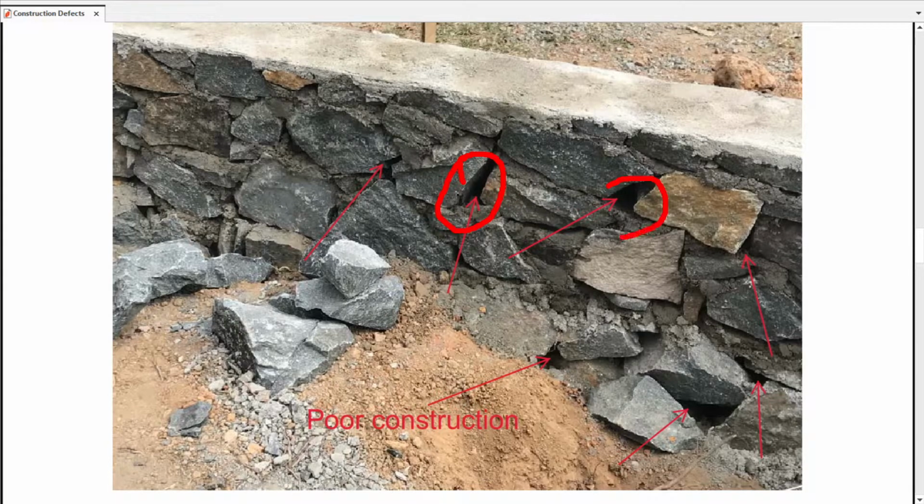As you can see here, there are very large cavities in improperly constructed areas. You can see so many issues here. This could lead to failure of the structure. If it is a single story building, there may be cracks. Once you put the load on, there will be issues in the structure. Therefore, you have to properly fill these gaps with mortar. As you can see here, they have put the mortar there, but they haven't put the mortar here. Therefore, we have to properly fill the gaps between the rubble in the foundation.